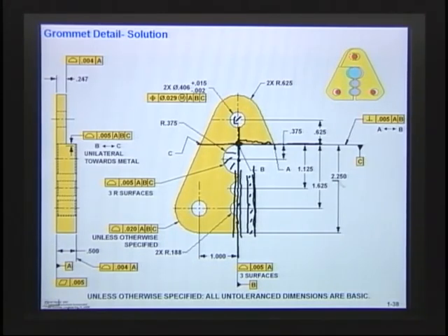They could come down 2.250, come down, and then they would touch spots. And as they touch spots, they're going to find out how much they're off that spot. And sometimes they do it like a whisker diagram, that if they touch a spot over here that's supposed to be 0, and they find out, well, it came in at +5. Then they're going to check another spot, and they said, well, that one came in at -2, right? And then if I did that, I can come in as a designer, I can collect that data even from the coordinate measuring machine, input, and I can connect the dots and I can actually draw you the picture of what the part is supposed to look like.